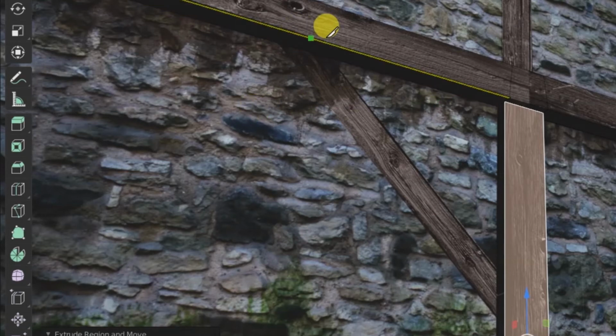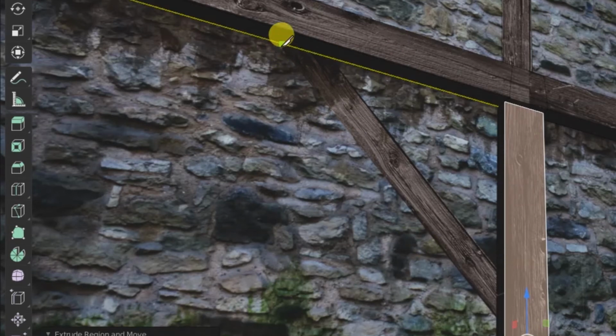But the reason why I'm looking at it right now underneath the beam here is it's really easy to click over here. If I click over here and then I tried to click over here on this edge, if I were looking at it from above or straight on, I might not know whether I was clicking here or here. So if I try to cut the air between here and here, nothing's going to happen, and you're just going to get frustrated, or maybe you accidentally cut some part you're not aware of. So make sure you're cutting from this line. You're actually cutting on the surface.